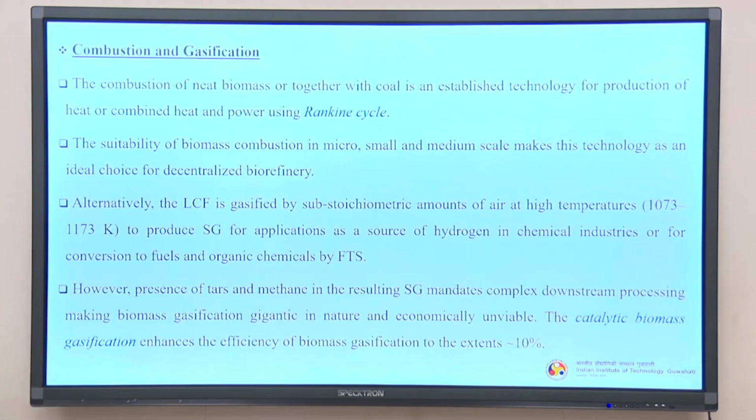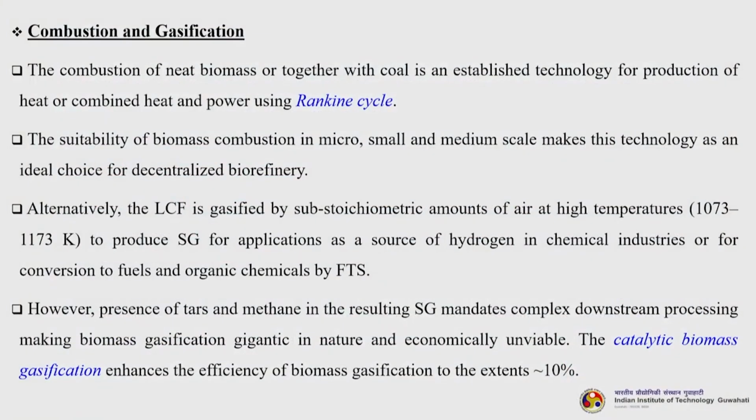Okay. So, the first process is combustion and gasification. The combustion of neat biomass or together with coal is an established technology for the production of heat or combined heat and power, the CHP, using the Rankine cycle. Okay. The suitability of biomass combustion in micro, small and medium scale makes this technology an ideal choice for decentralized biorefinery. Alternatively, the LCF is gasified by sub-stoichiometric amounts of air at higher temperatures, almost 1073 to 1173 Kelvin, to produce syngas for application as a source of hydrogen in chemical industries or for conversion to fuels and organic chemicals by the Fischer-Tropsch synthesis, FTS.